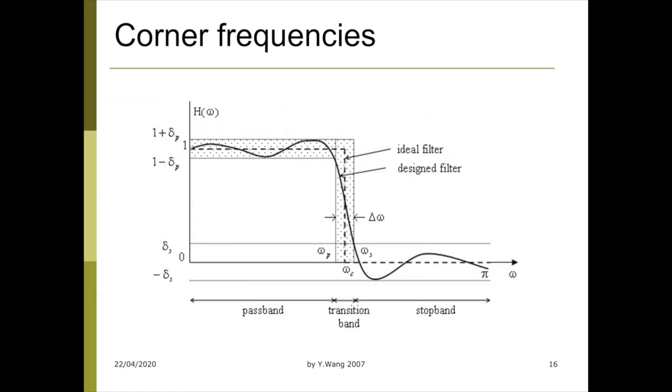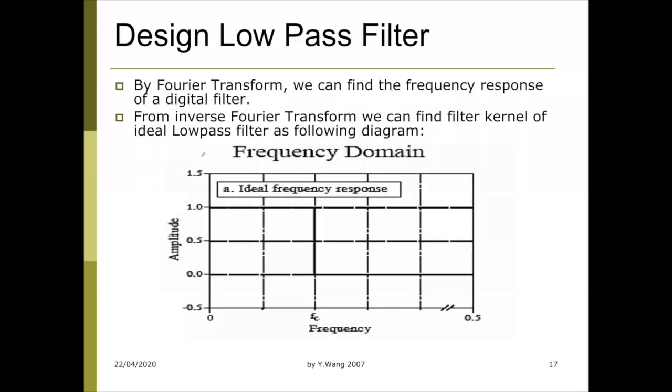Design a desired curve of the filter, which is defined with certain numbers, certain regions, and the filter realization, or filter design algorithm, ideally will fit within the error region of the filter you designed. So think about this: if you think back to the SP2 we used so far, you set some sort of A pass and A stop. Those are the error tolerance you give to the filter design algorithm.